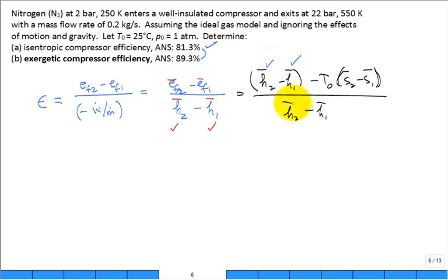So I got these values done. I've got my dead state temperature. Notice it's 25 degrees C, right? Should we add 273 or should we add 273.15? I think I talked about it already. Just add the 15 and let your calculator handle it, okay? When in doubt, throw in the extra digit. Even though this temperature is only given to 2 significant digits, you're basically adding digits up to 5 significant digits, so the answer is still 2 significant digits of accuracy.